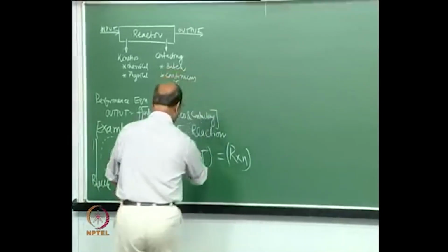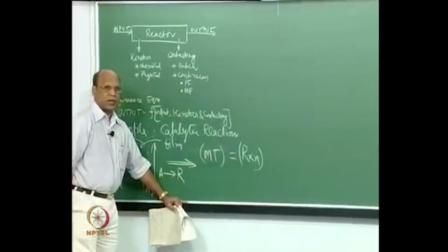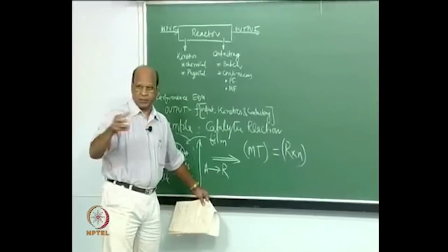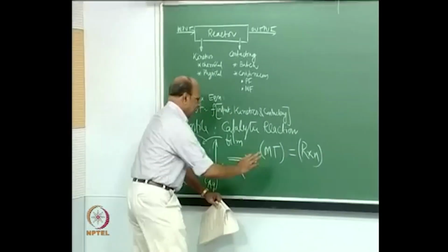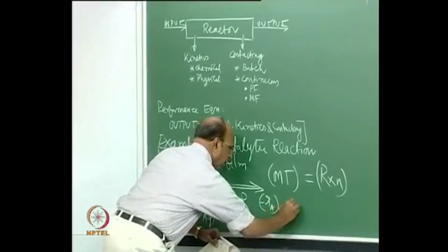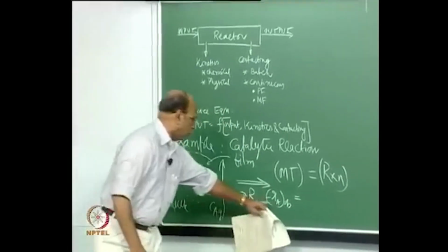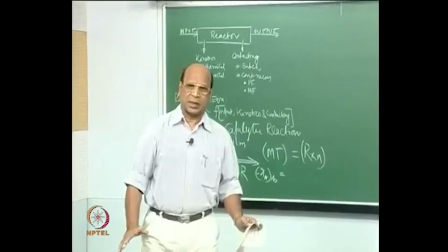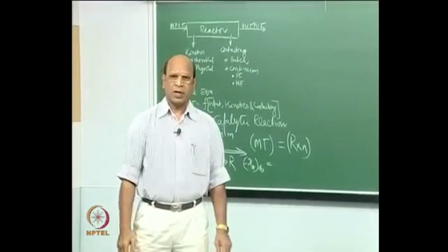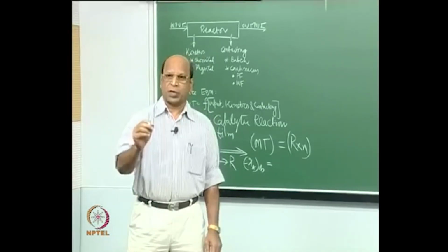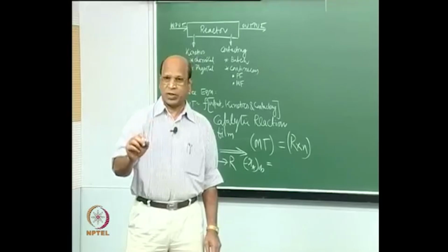So once I have these 2 steps, rate of mass transfer equal to rate of reaction, then for the reactant A, the equation again is minus r_A prime, this is the overall rate. You should not forget this, minus r_A prime. All heterogeneous systems will have only an observed rate, measured rate, overall rate. Different books use different names for this.